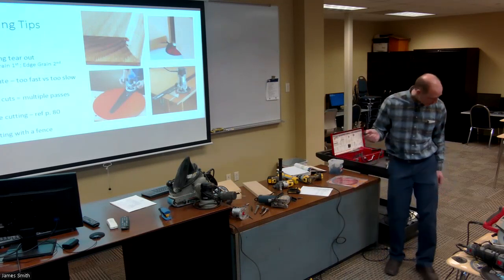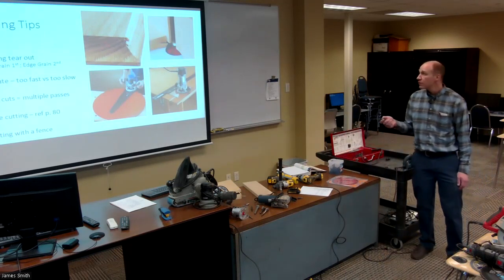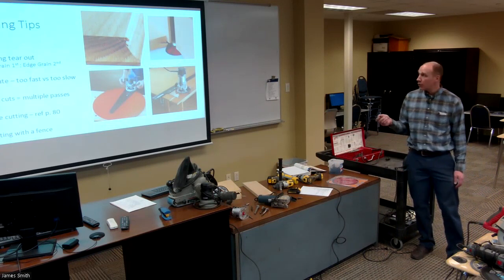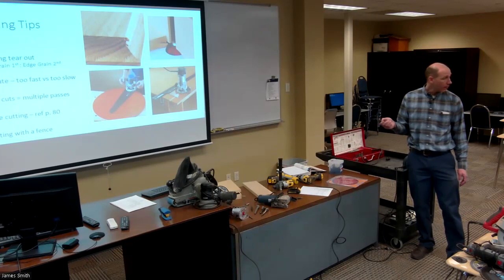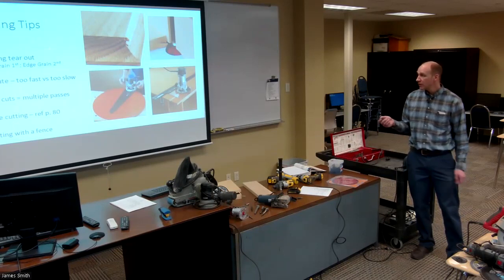Yeah, so there it is. This is a picture that shows what happens if you route the edge first and then the end. You get that little bit of tear out, okay? So you always want to do the end grain first, okay?